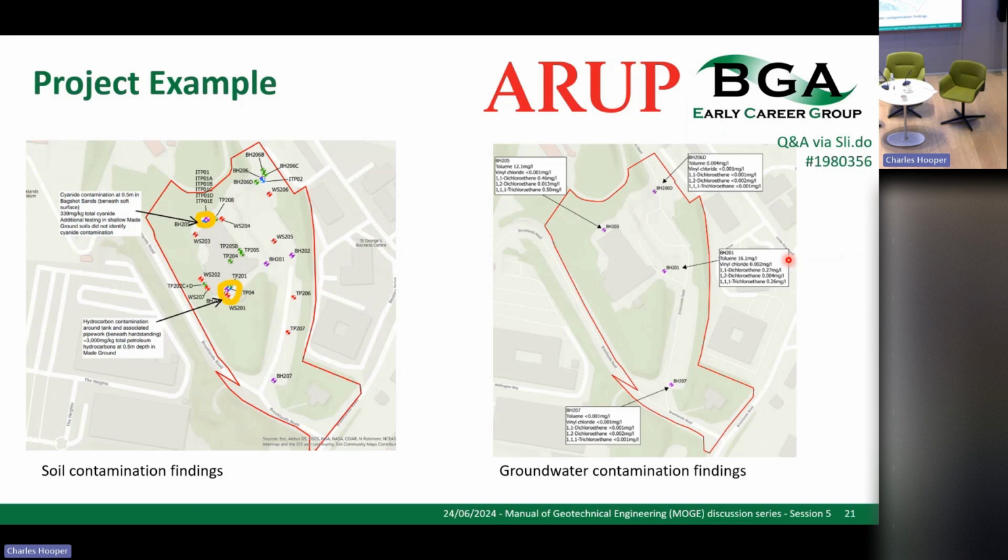So in the northwest, we have cyanide, 300 milligrams per kilogram, very high concentrations for a soil with no real reason. And more interestingly, we found it in the gravels, the natural soil. So we would expect to find that in the ground, but the overlying materials are actually clean. So we went back and did a bunch more testing of it, which we'll talk about in a bit. In the south, we have some hydrocarbons around the tank, so there's a leaking fuel line from it. Not really a big issue, but 3,000 milligrams per kilogram, just immediately adjacent to it.